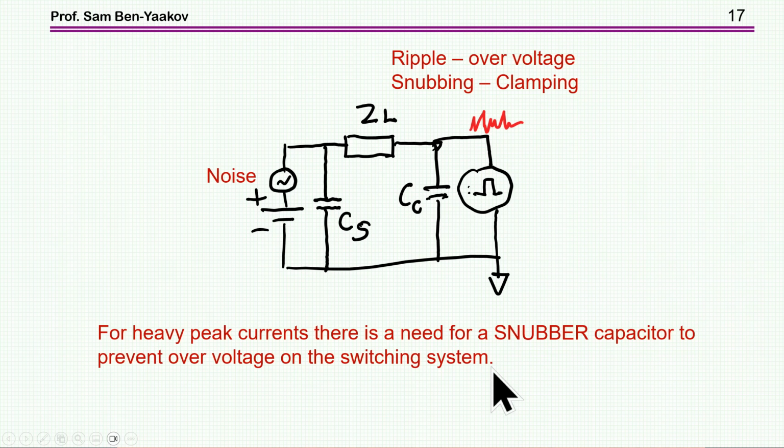And this is a case in which you would need a snubber capacitor, which is designed specifically for this application, in which you have very high dI/dt and very high current, so they can tolerate it. I'm not going to talk about it in this presentation because I'm limiting myself to the lower power, but this is another subject that hopefully I'll discuss in a forthcoming video.